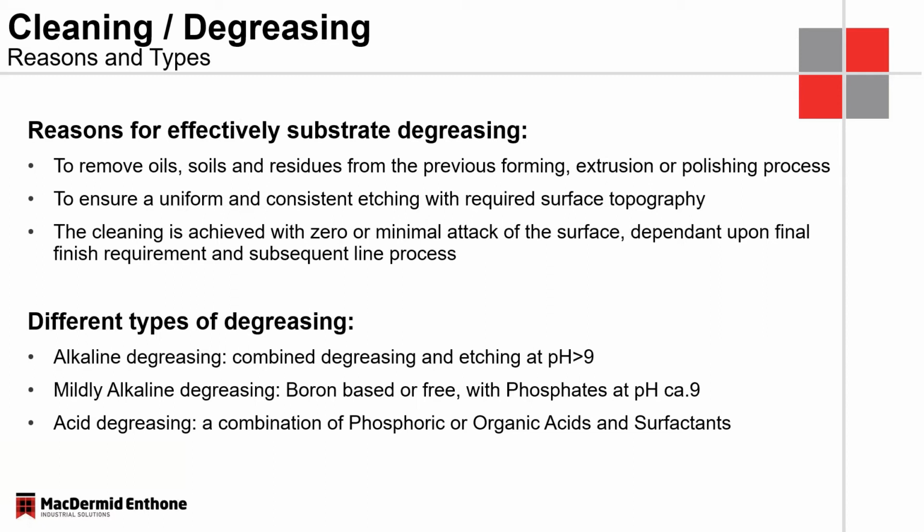So this is really to remove any residues, any soils, oils, cooling liquids from previous operations, whether that is from the extrusion, polishing, forming, or any sort of machining here. So these have to be completely removed to make sure that we have a good attack from any subsequent process step.